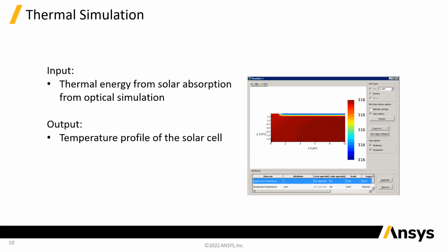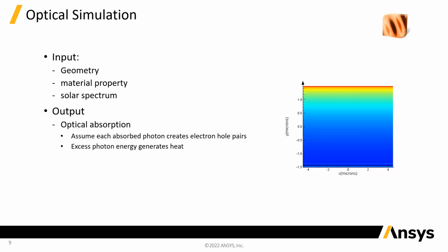Well, FDTD means finite difference time domain. It's a numerical way of solving Maxwell's equations, where the finite difference means that you break down your simulation space into grids of finite spacing. So in your XYZ coordinate, you'll break it all down into rectangular meshes, and then you'll have multiple grid points in your 3D volume. And for each of those grid points, you will know what material is present there, and then how light is going to behave at that grid point.